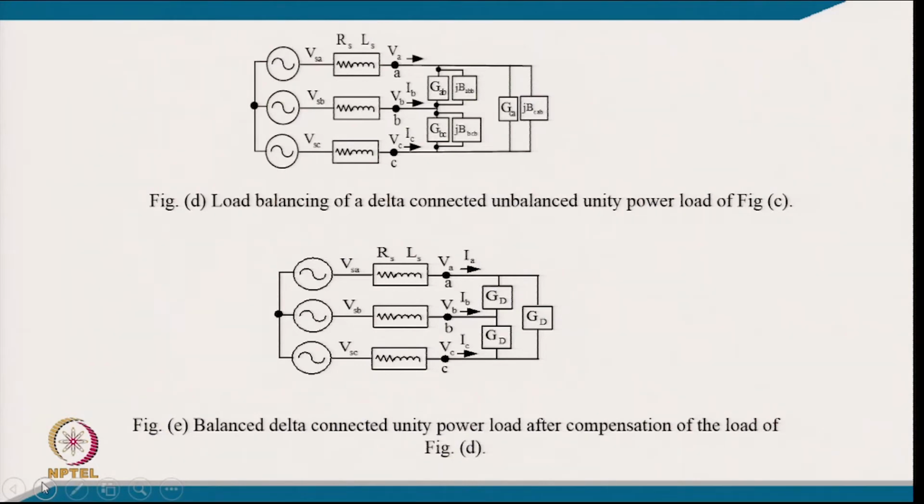So now we can put another set of compensator, typically here, where we are connecting this compensator for providing the balancing. I mean balancing in the sense of what Steinmetz has given, that even a single phase load can be realized as a balanced load. Any unbalanced resistive load, these three resistive unbalanced loads, by putting a compensator, this three phase load can be realized on this system as a balanced and resistive load. So, this can be represented as equivalent to a delta connected resistive load with the conductance of GD, all equal, as a balanced load. It means a lossless compensator, meaning capacitor and reactor, can provide power factor correction, making them resistive load and then equalizing them or balancing the load. Then you will have a three phase balanced current flowing into the supply system at unity power factor, because it is equivalent to a kind of resistive load.